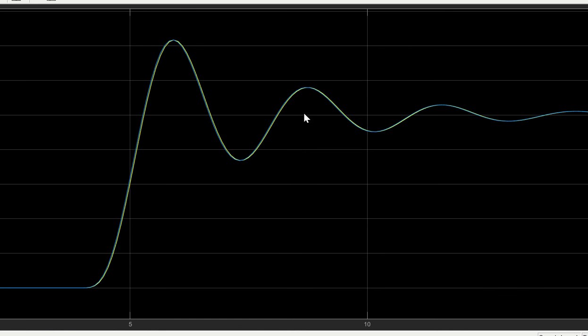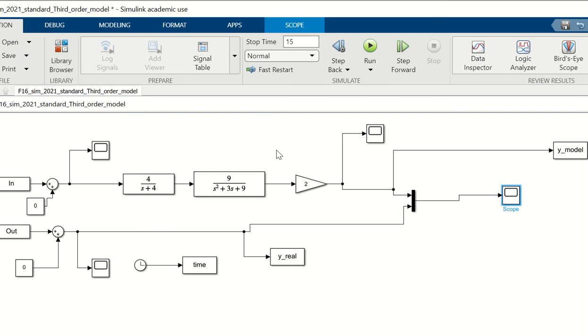So now we've managed, with the perfect match, we can say that these are the parameters which now represent a reasonable model for this given system. So you change that one first, then the frequency, then the damping ratio, and then the time constant of the pole. This is like a little actuator that moves the elevator, and this is like the flight dynamics of the plane, which has been modelled by a little second order system, and that's a gain on the system. So go for that one first, then those two numbers, then that one, and then those.